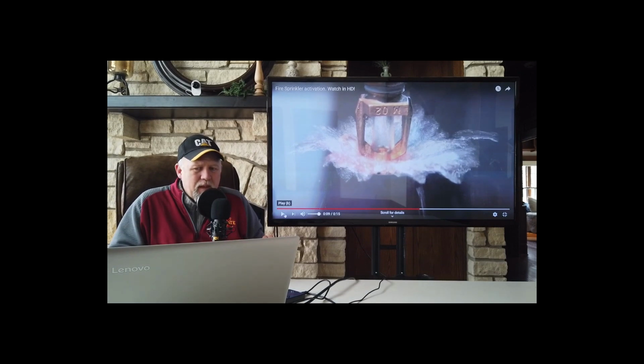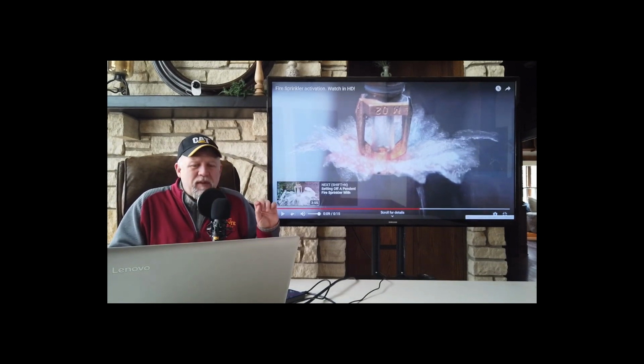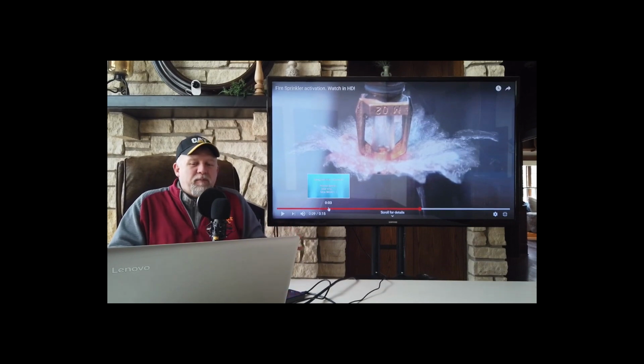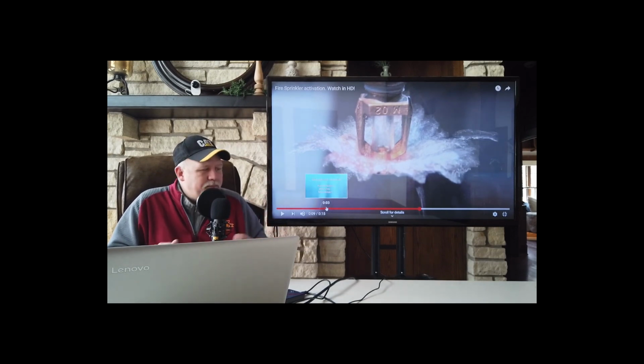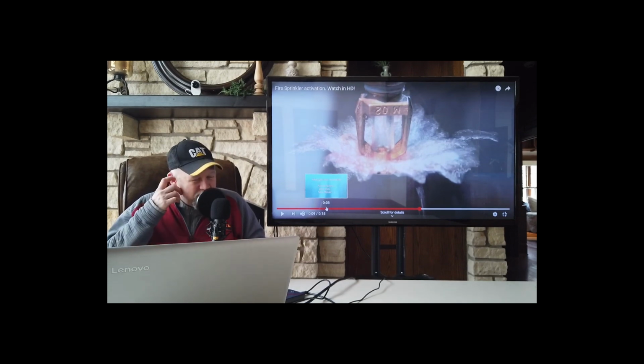Now, something important about these sprinkler heads: that little piece of glass, it's a piece of glass. So if it is hit, or if it is poked, like somebody throws a football or a baseball, maybe in an apartment or a dorm, a hard enough physical shock could break it, and the sprinkler won't know any different. It'll operate just the same as if that sprinkler had broken because of a rising temperature. And that is the part that makes building owners and facility managers nervous, especially in apartments and dorms.